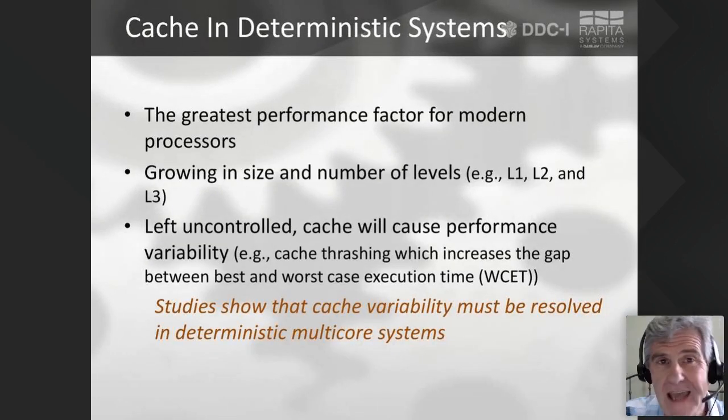So even with all of that, and you set up an effective scheduling implementation, the underlying hardware induces interference as well. It's pretty easy to visualize managing interference and coordination for peripherals that you add to the system, for example, a PCI device. Most of your developers will understand that and how to coordinate the access to that. But the platform you choose has some interference natively, especially with regards to cache and memory bus arbitration. Shared cache contention is the greatest performance factor for today's processors.